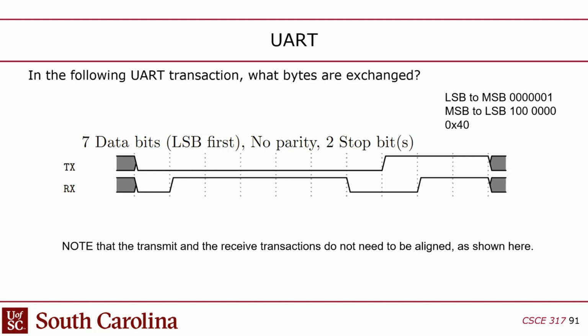You're changing the bit. So you don't know when you're reading these bits. You know how frequently to read them because of the clock period, but you don't know when to read them exactly within that period. So if this guy happens to read on that edge, then you're going to get an error. And there's just nothing you can do to avoid that. It's just random chance. It just depends on how your clocks are aligned when you generate them.